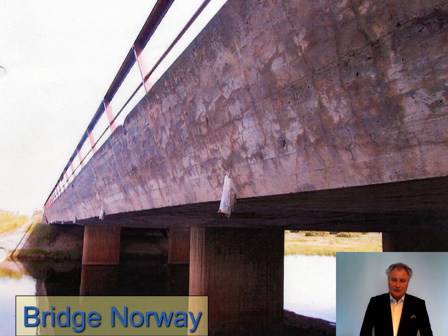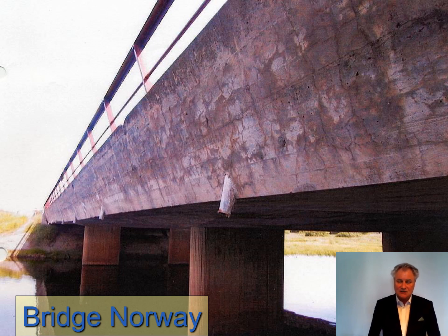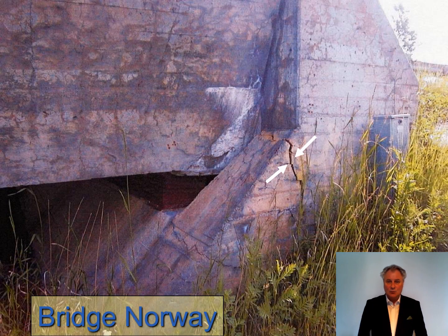Here is another example from Norway. You can see this typical map cracking on the concrete on the top of this bridge. But in this case, the main forces have been concentrated in one point, and as you can see in this part of the bridge, you have one major crack. So this is just showing the forces of the expansion of AAR when it has happened in concrete over time.